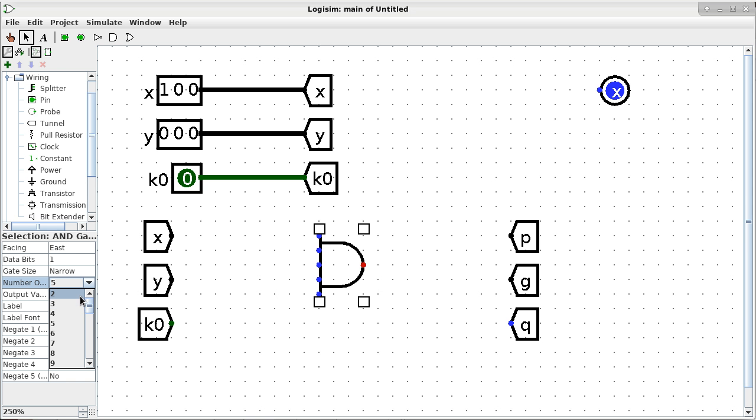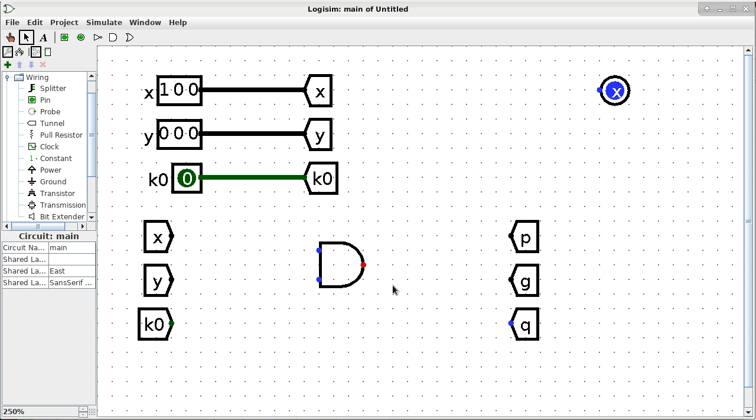So I'm going to make it a requirement after this assignment that you cannot have input pins that are not connected in a gate. In other words, if you use a 5-pin gate here and only use 2 of the pins, I'm going to be okay with this homework assignment because I didn't specify that requirement. But from here on, if you only need 2 input pins, then you make the gate to only have 2 input pins and not have more input pins than you need.